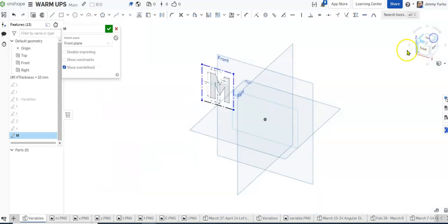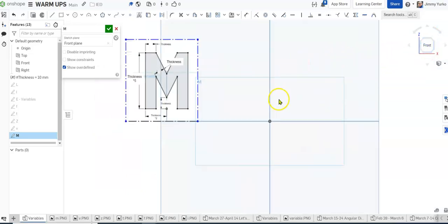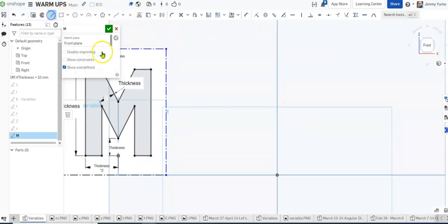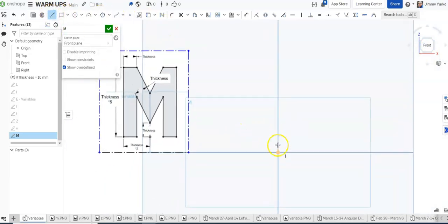So again, I'm going to use the right plane as my axis of symmetry. We use the origin to get ourselves started. I'm going to take the line tool and we'll draw from the horizon line to the left of the origin, and just go across, up, make sure I'm going horizontal, now vertical. I'm above the origin, and let's see, I'm just going to escape on that line tool so I do it again.